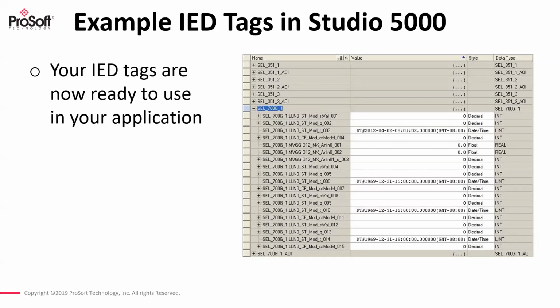So as you're commissioning an application, no more do you have to look at Excel spreadsheets and other devices where the substation automation guys are looking at Modbus address 40,001, and you need to look into a separate tag to figure out what 40,001 actually represents. It really helps to save a tremendous amount of time, because the automation side is utilizing the same tag name as the substation part.